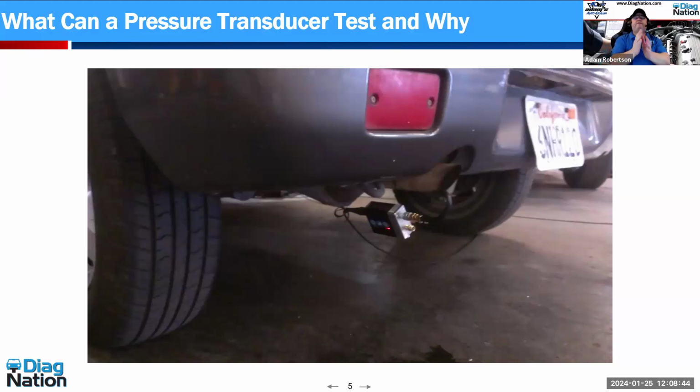If I have a firing order of 1 3 4 2 and cylinder 1 fires and the expanded gas comes down the exhaust, there's going to be a period between cylinder 1 and 3 where atmospheric pressure is going to go back into the exhaust. So basically what we have is pulse, atmospheric pressure, pulse, atmospheric pressure, pulse.